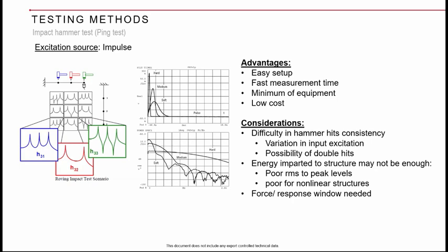Whereas in reality, when you subject them to a higher excitation level, such as actual engine excitation or actual shaker excitations at higher G levels, you will see that they will have micro slippages, and therefore the frequencies will be quite different. So in such cases, impact hammer test will give you higher frequency than the actual test requirement, which is quite a different indication.